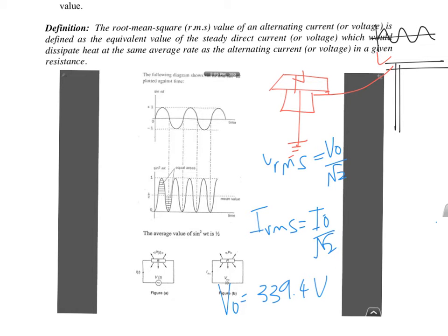So you need an AC to run your transformer, and the transformer can step up and step down the voltages easily. So why do they want to step up the voltage? We will learn that in the next part, but I'll just tell you briefly what they do. When they step up the voltage, it is during the transmission over large distances, so that the current in your cable is small, so you have less power loss as heat in your cables. But just before the consumer uses it, they will step down the voltage, so that in case you accidentally touch the live wire, the danger of a large current passing through you is not great. So there will be a small current passing through, so you will not die immediately. So that is why they need to step up and step down the voltage. So that is the advantage.